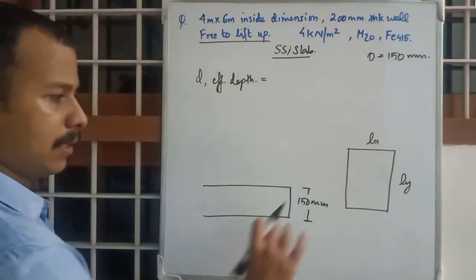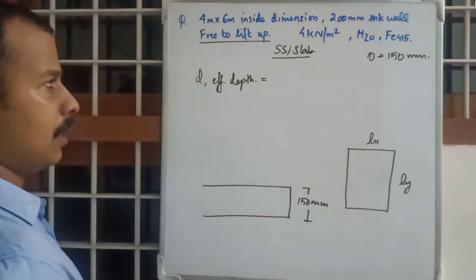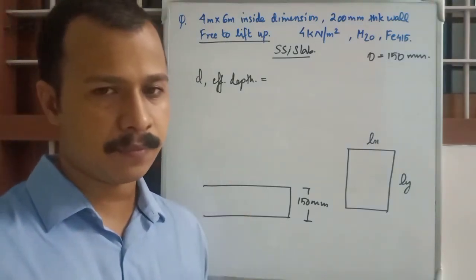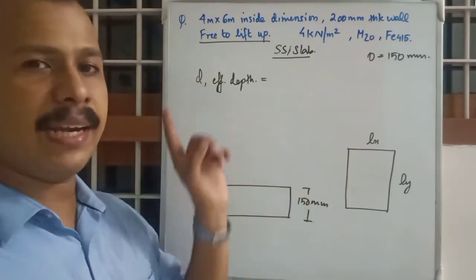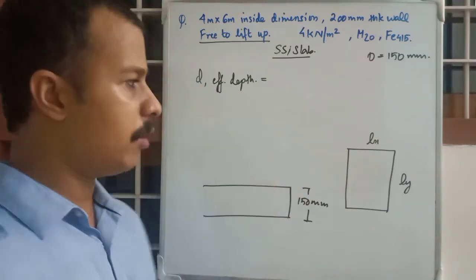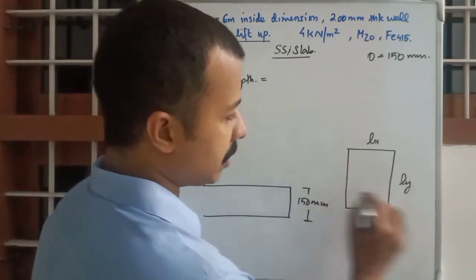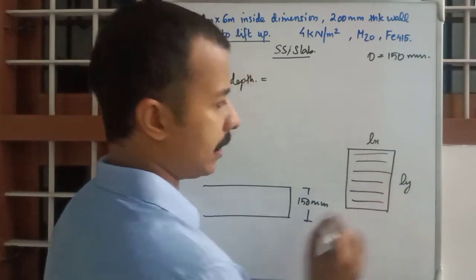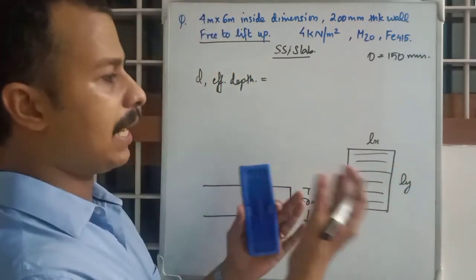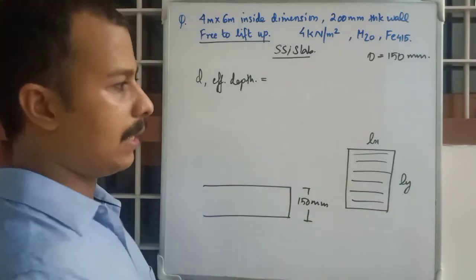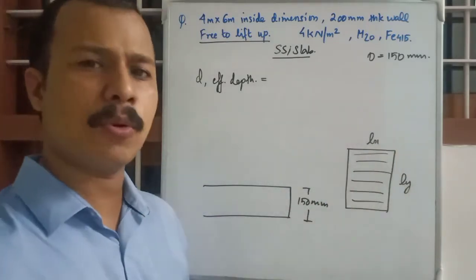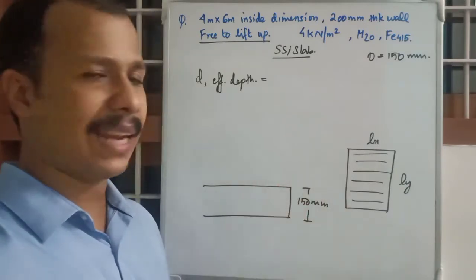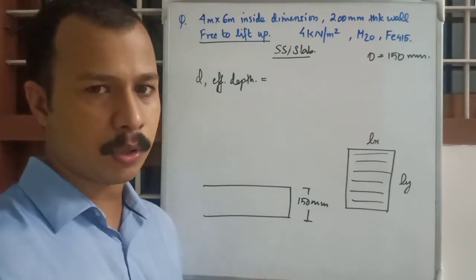We will be having two effective depths, dx and dy. Why? In one-way slab we were only designing main reinforcement in the Lx direction, and we used to crank it onto those sides, and the Ly direction was just distribution reinforcement because it was not so relevant in one-way slab. But in two-way slab both directions are important.